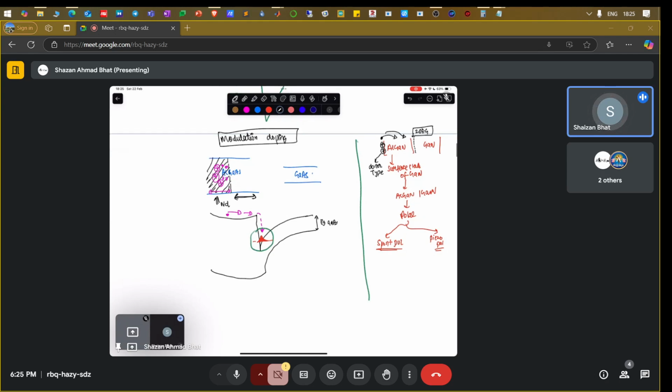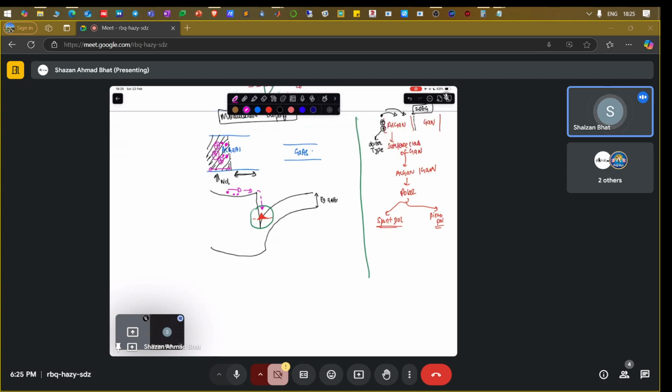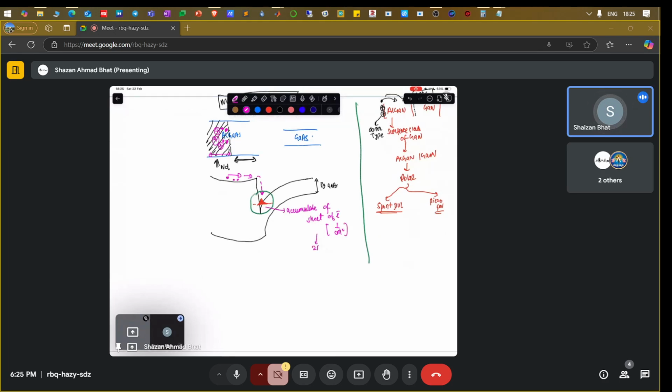Here it's opposite. Here you have doped the AlGaAs region. The doping has released those electrons. They are donating the electrons, and those electrons settle in the two-dimensional electron gas at this particular region, which is basically an accumulation, a sheet of electrons. That's why, if you write the charge density, you write it per centimeter square here, not per centimeter cube, because it's a two-dimensional sheet charge, a two-dimensional electron gas.